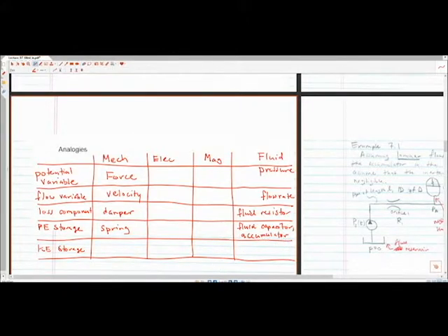All right, kinetic energy storage in a mechanical system. What do we have? Masses, right? And then fluidic system. One term we barely introduced on Friday, it may not be fresh. So fairly similar. It's actually the mass of the fluid flowing. So we have fluid, it has a certain velocity, right? So it's going to have momentum associated with it. And so we call this an inertance in fluidic systems. But it's essentially the same idea, right? So you have a solid mass. When we talk about mechanical systems, we're usually talking about solids, right? But with a fluidic system, you're actually talking about a volume of fluid moving in some sort of channel or some sort of vessel, and that has a certain kinetic energy storage element to it.